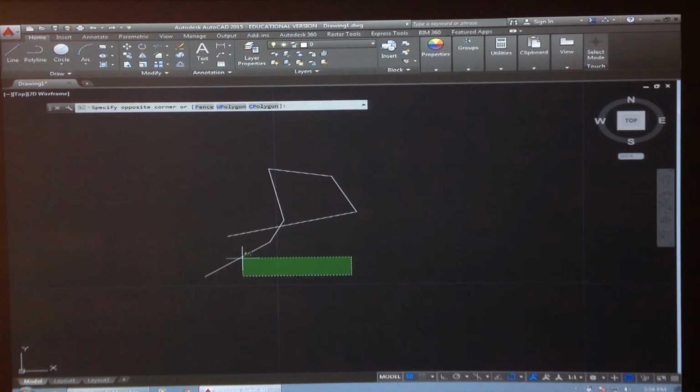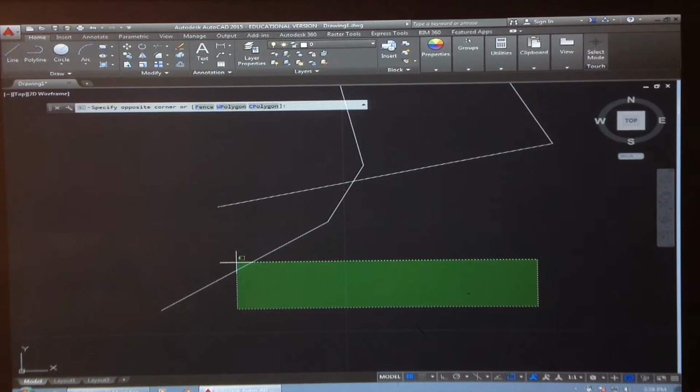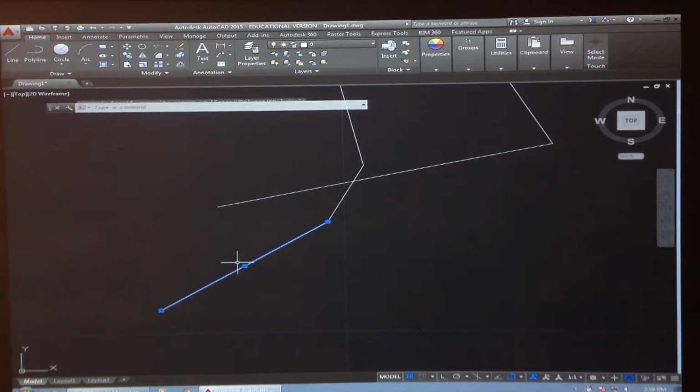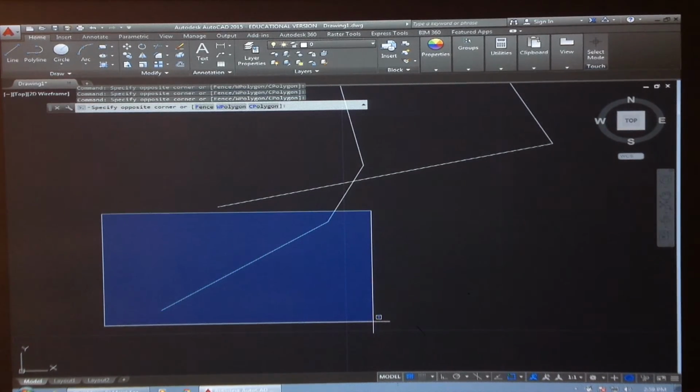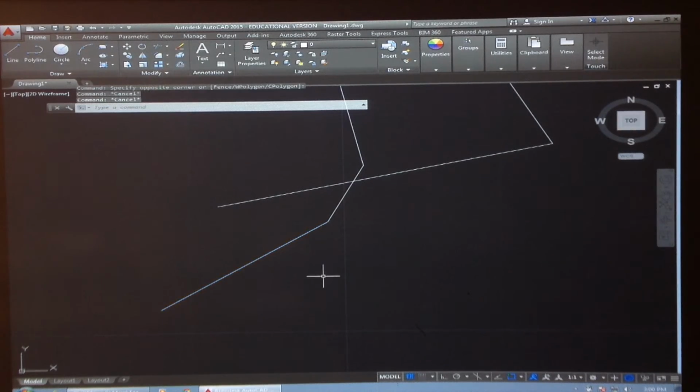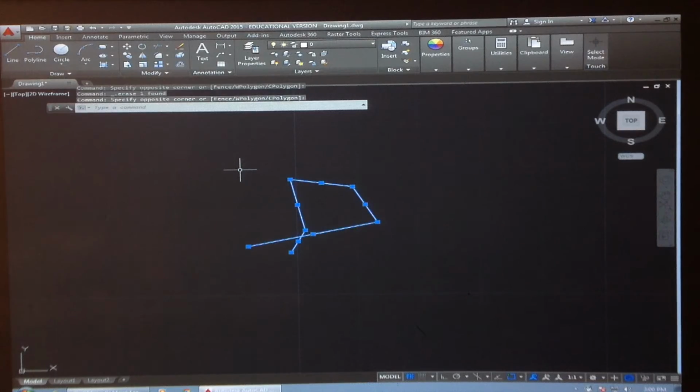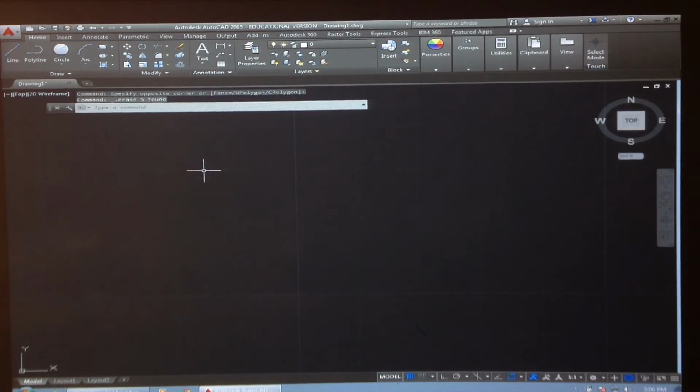Now watch the difference. If I just click right here, a little bit of the line, it still highlights the whole line. Escape. But if I use the blue box and I highlight a little bit of the line, it won't do it. That's because you have to highlight the entire line with the blue box. Whereas the green box, you can just highlight a little bit. And that is just some basic key features and functions you can do just to start you off.